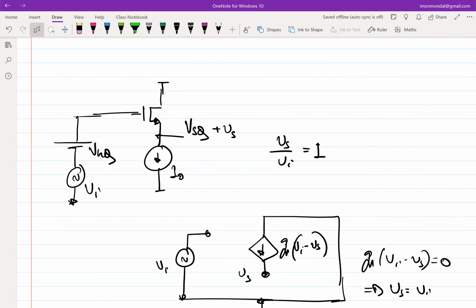Okay, in the same direction, not in the opposite direction like a common source amplifier, where the signal swings are in opposite directions between the gate and the drain. Here, between the gate and the source, the signal swings in the same direction by the same amount. Make sense? Okay, fine. So since this is following the voltage, this seems to be an interesting configuration, and let's say I want to understand what happens.